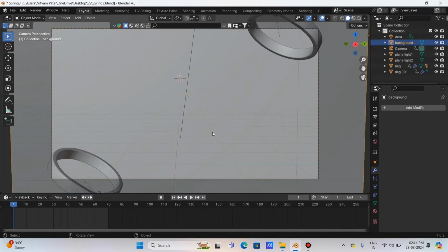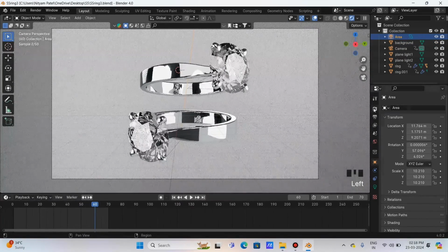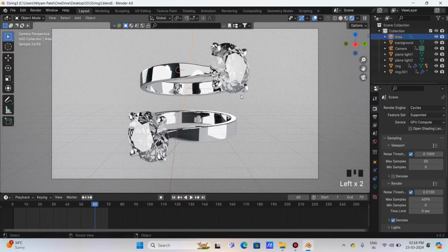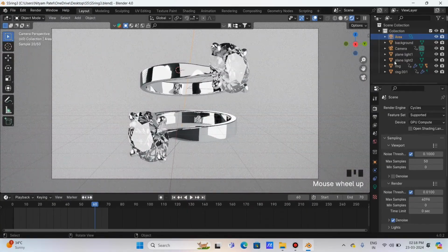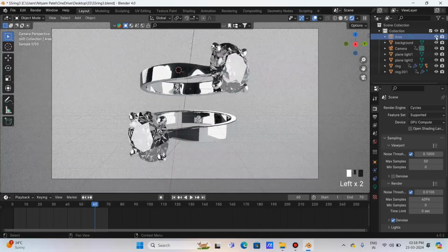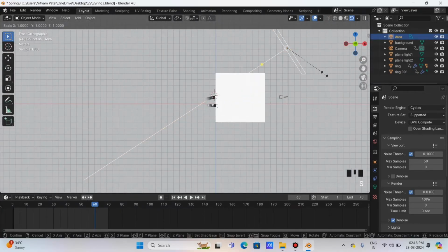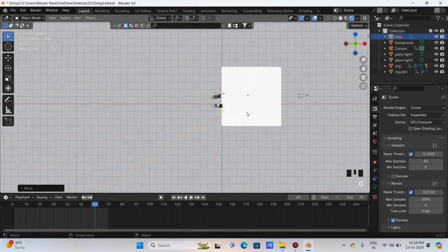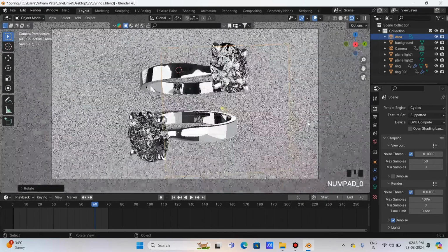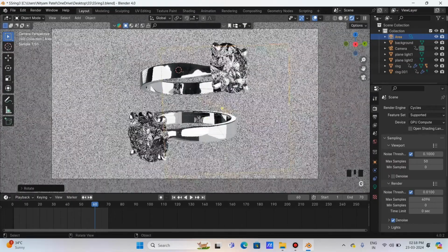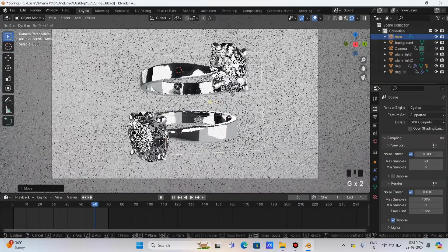So now it's time to set up the lighting and background. So I'm going to the render view, and as usual it's too bright, and if you hide the lights one by one then you can see that the area light reflects too much. But here I don't want to stop the reflection altogether. Instead I decrease the scale size, place it very close to the ring and rotate it towards the ring. So as you can see the reflection on it, I think its reflection is fine.